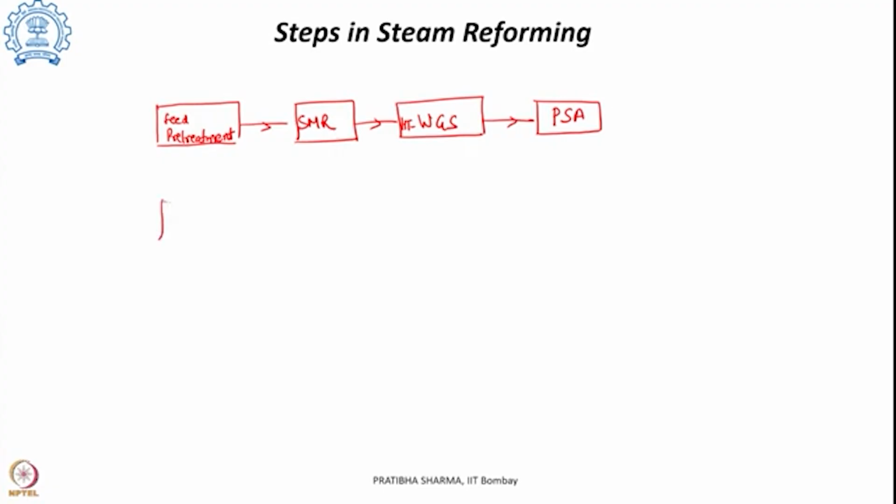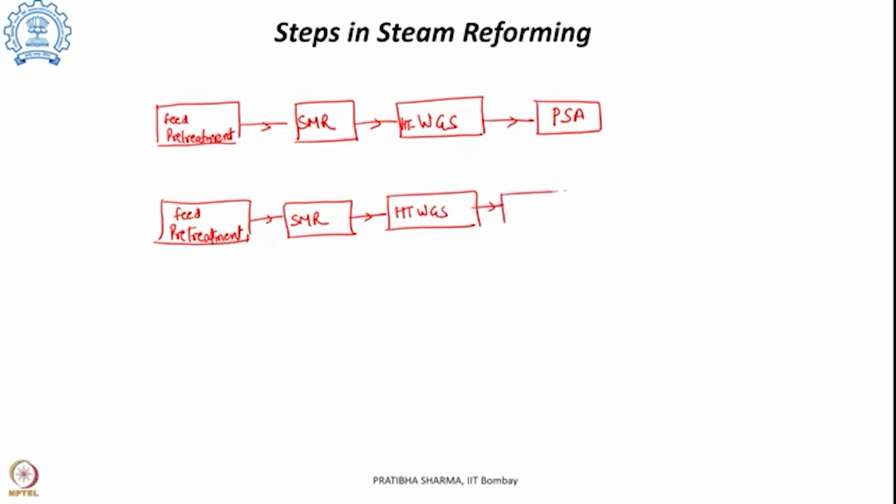However, if there is a change in the purification technique, like if we are using after SMR a high temperature water gas shift, a low temperature water gas shift will be followed if the final purification stage is carbon dioxide solvent based purification technique, to get pure hydrogen.